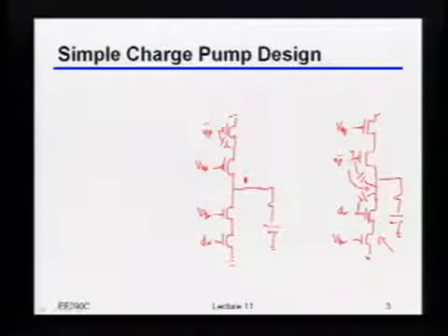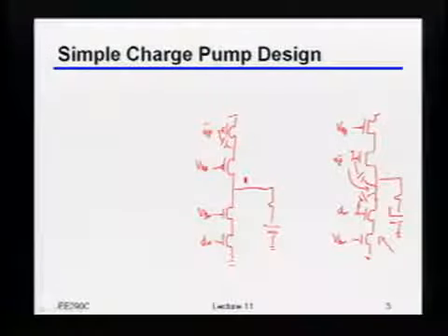But what else happens when you turn a switch? Ah, there we go, charge injection, right? So here, for this switch, looking down, all it sees is the parasitic cap and maybe the output impedance of this current source, right? Looking up, it sees this big loop filter. That loop filter probably has lower impedance, right? So most of the charge from that switch is going to go into the loop filter, right? Whereas over here, on one side, I've got basically the power supply, right? So I'm still going to get some amount of charge injection, but at least some amount of it is going to get swept out into the power supply, okay? Does that kind of make sense to people?